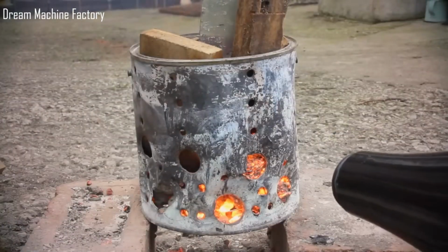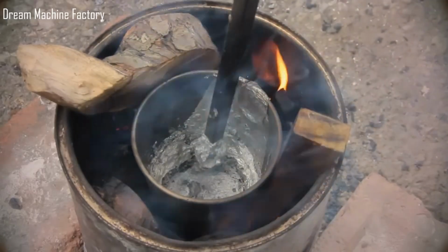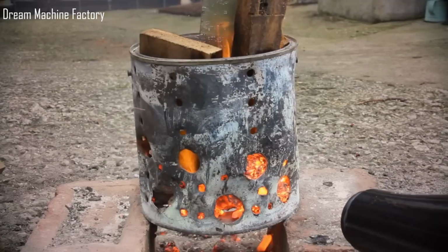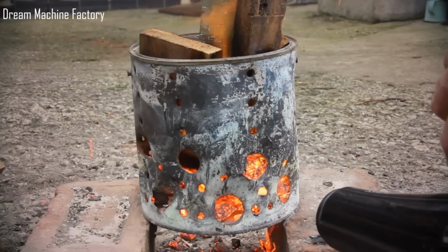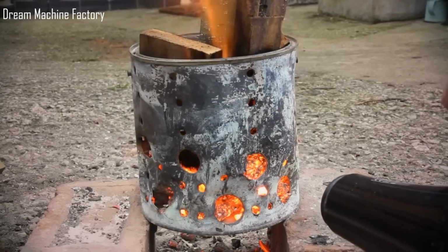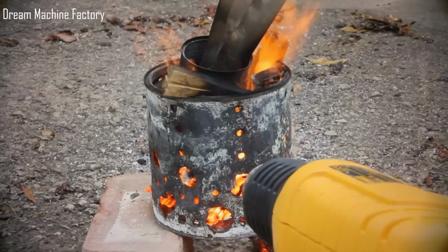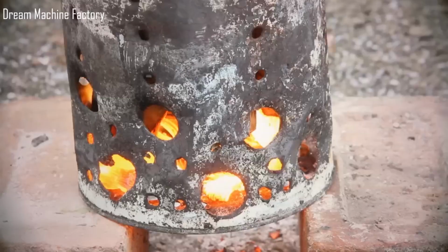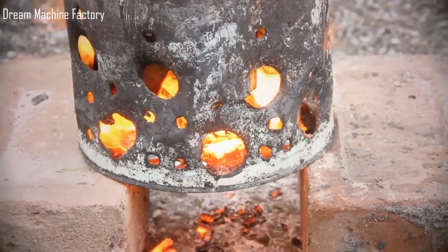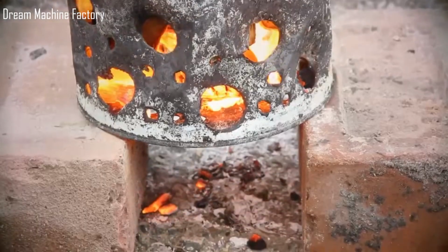An air supply is vital for reaching the high temperatures needed to melt aluminium, as wood alone often burns too cool. By forcing extra oxygen into the furnace, combustion becomes hotter and more efficient. A hairdryer is the easiest option, but a hot air gun or small blower works well too. Position the furnace on 2 bricks so air can enter from underneath and ash can fall through. Direct the airflow toward the base holes, ensuring a constant, strong oxygen feed throughout the melting process.